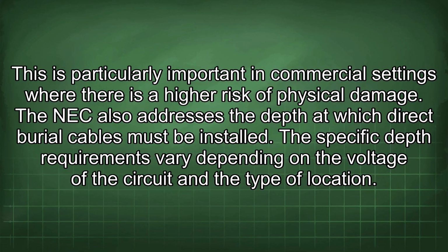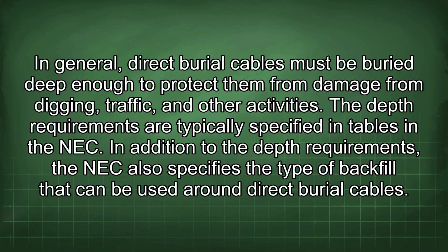The NEC also addresses the depth at which direct burial cables must be installed. The specific depth requirements vary depending on the voltage of the circuit and the type of location. In general, direct burial cables must be buried deep enough to protect them from damage from digging, traffic, and other activities. The depth requirements are typically specified in tables in the NEC.